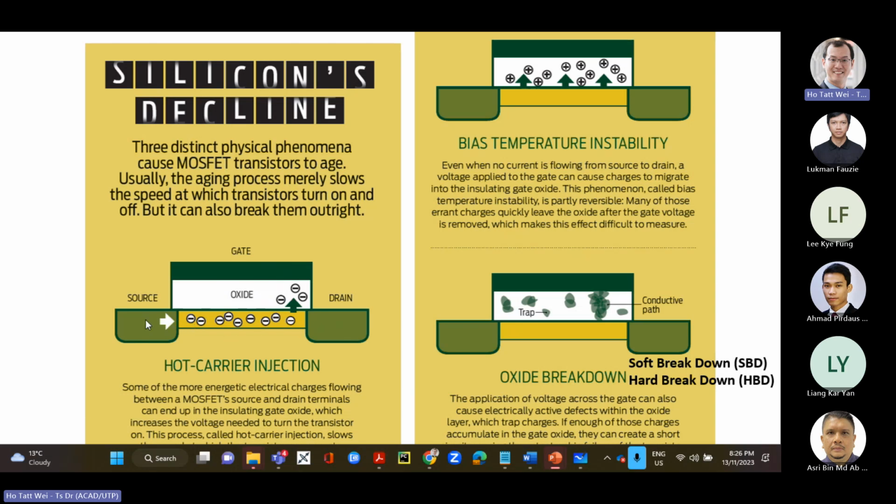They are moving very fast, and they're called hot carriers because they're moving very fast and slamming into the lattice and all that. They are not just being pulled this way, they're actually being pulled this way as well as upwards, so they're being slammed into the oxide, and they can get stuck and embedded directly into the oxide. And how can this happen?